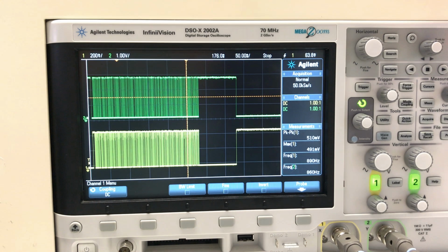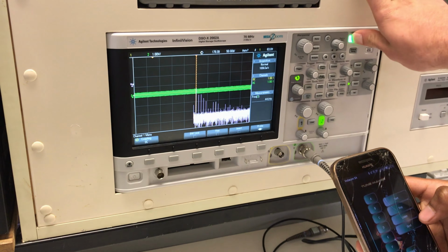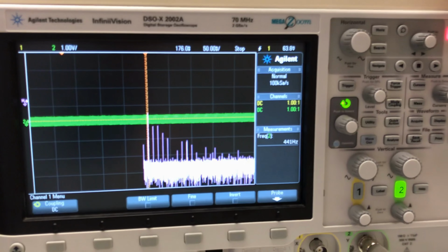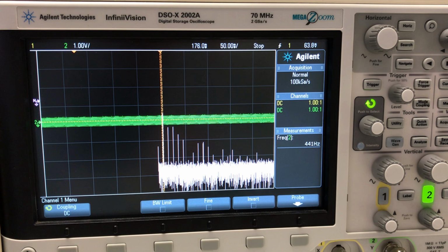Here, we can see the waveform generated from the oscilloscope probes that are put across the input to the speaker. An FFT has been performed on this waveform and the output can be seen here. Due to the note A being the musical note which was played, the FFT here can be seen to be 441 Hz, which is very close to A's frequency of 440 Hz. This satisfies system requirement 8 and system requirement 6.